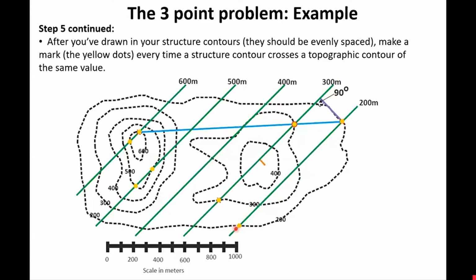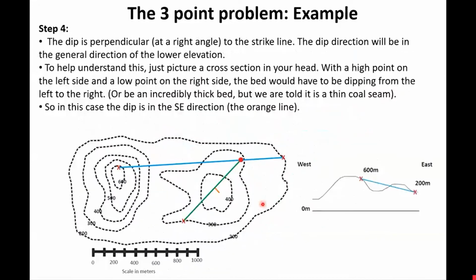And so we know that we can use the law of V's, but we know that it doesn't exist in the valley here. So we have to think about a couple of options on how we can project the contact across the entire map area. Remember, we've got this valley in between the two hills. So our surface actually exists in the air. It's been eroded out. We've got a river there, eroded out the ground underneath our contact.